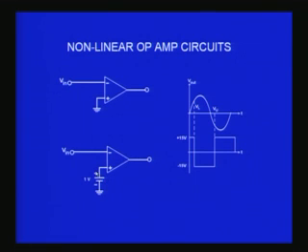Then over this 1 volt, when the input exceeds by 140 microvolt, the output will become minus VCC, and when this input becomes less than 1 volt by about 140 microvolt, then the output will go to plus VCC. So these VL and VU thresholds are now shifted from simple plus or minus 140 microvolt to 1 volt plus or minus 140 microvolt.